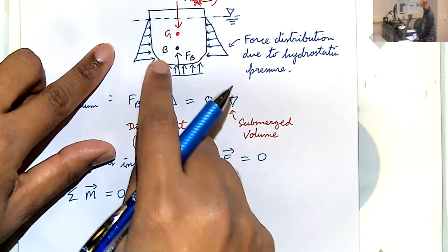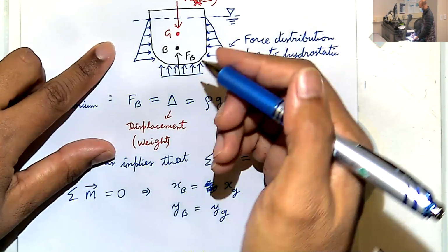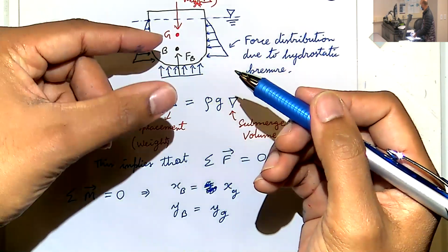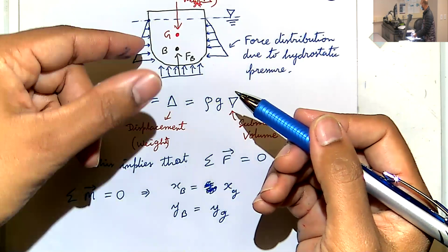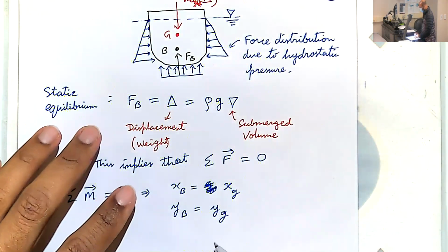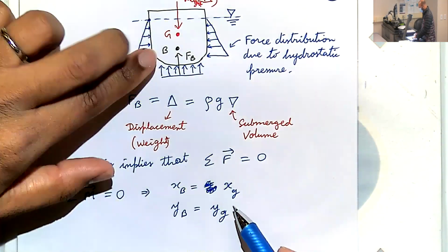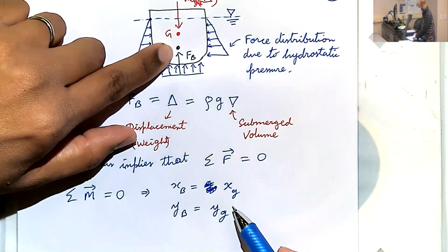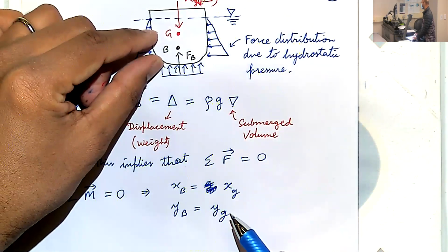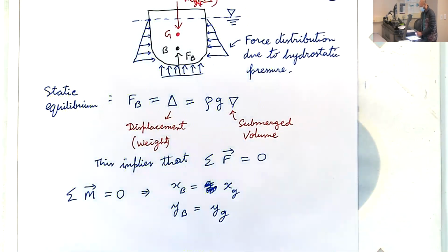If I move the G out of paper, that'll create a pitching tilt, okay? A list, and the ZG, of course, is not equal. You see there's a separation between the Z coordinate of B and Z coordinate of G. That's okay. That's actually essential to keep it this way.